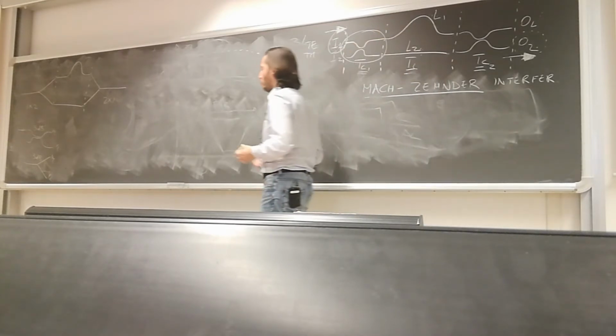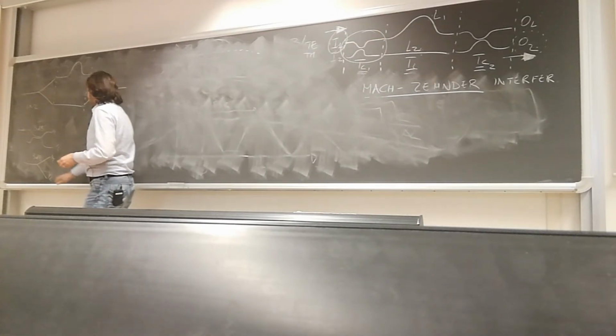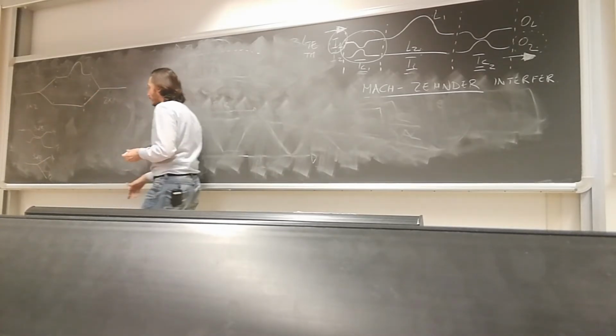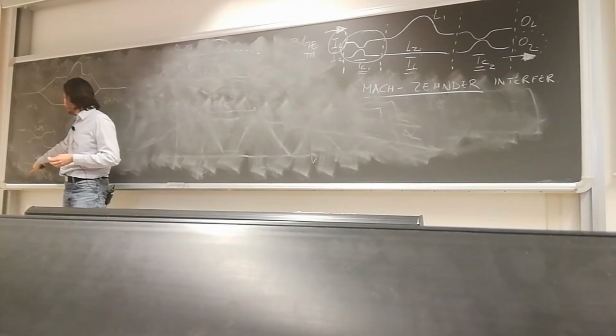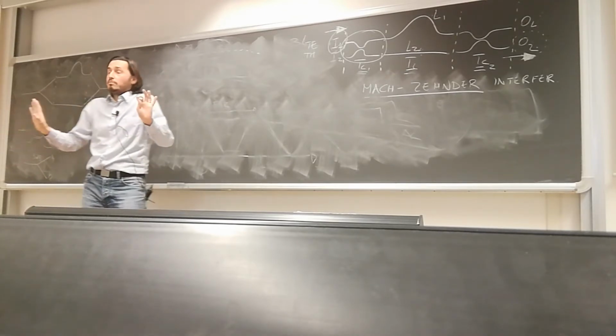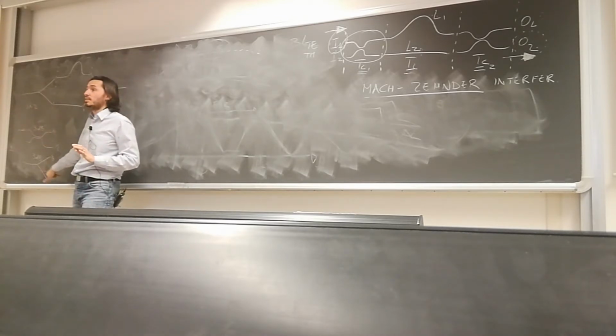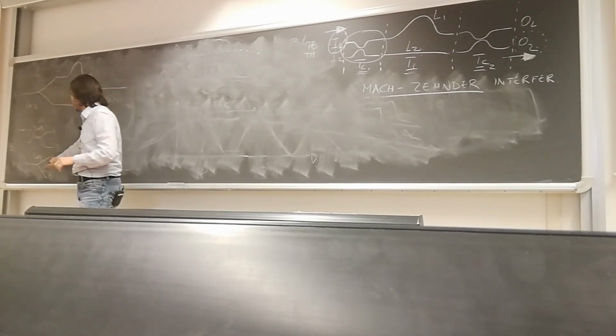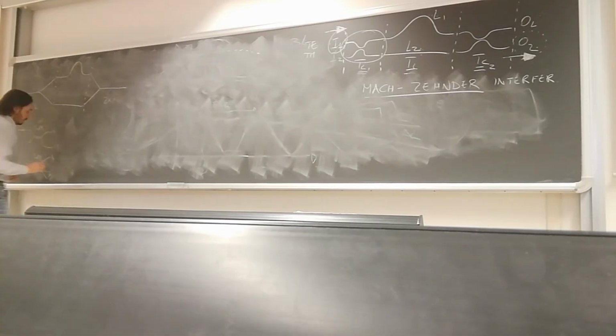Again, the phase is not an option. I don't know if you have been told to focus on it, but in a 3 dB Y branch, because of the symmetry of the structure, the phase is the same. They share the same phase, okay? Delay is the same, the phase is the same. So if I look at the phase difference between these two ports, the phase difference is 0.